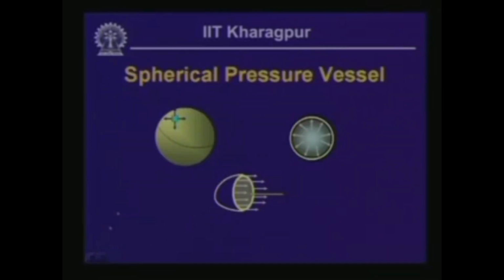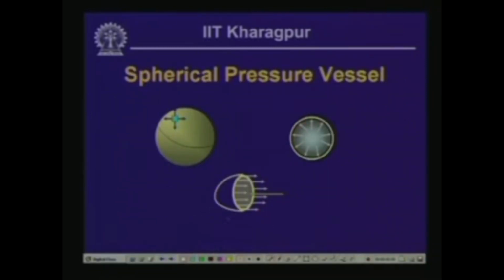We had evaluated the values of the stresses, and if you remember, for a spherical vessel of this kind, the stress that exists is sigma, both in the x and the y direction. We had written down the resistive force, which is sigma times area, equal to sigma times 2 pi r t, where r is the internal radius of the spherical vessel and t is the thickness.